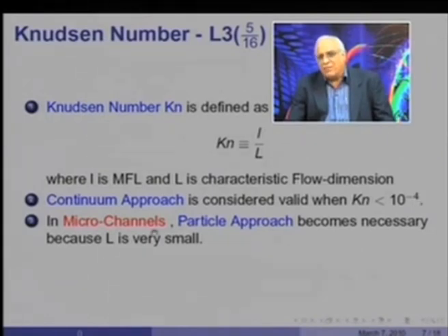Now, today we have microchannels whose dimensions could be of the order of microns or tenths or hundredths of microns, and clearly the dimension L itself would be comparable to the mean free path length, and therefore in such a case the particle approach would become necessary.